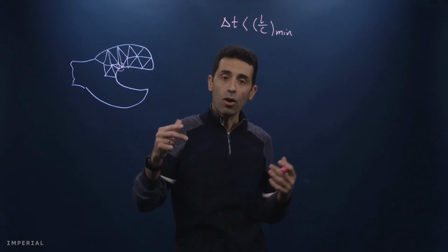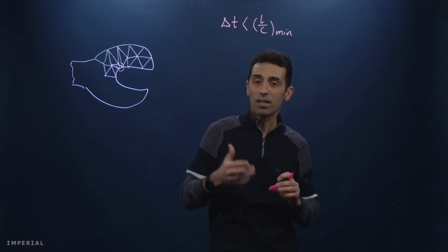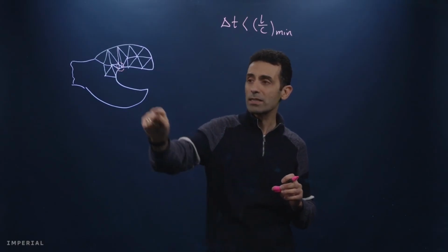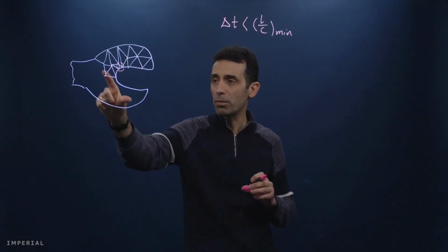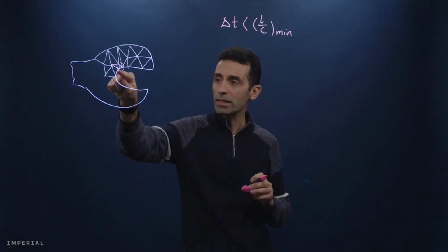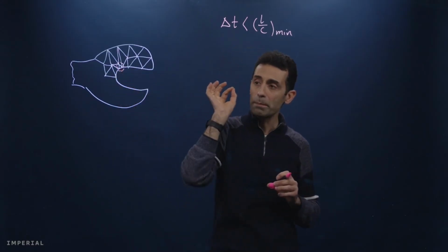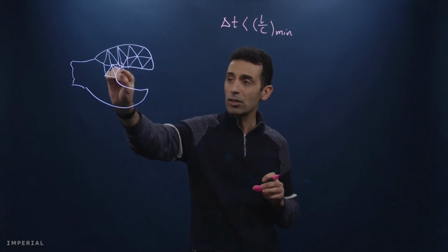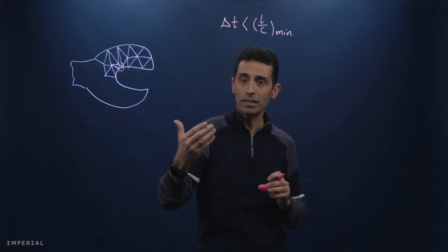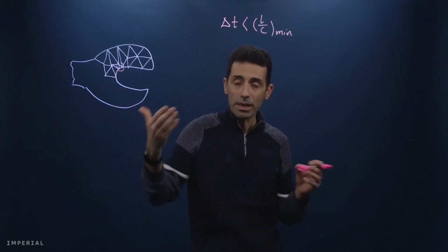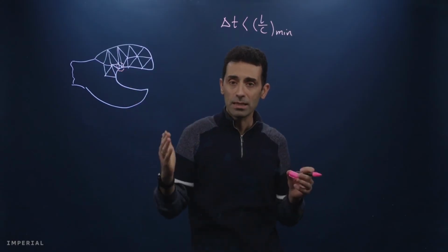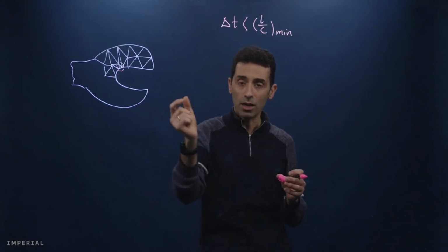These sort of elements are often created because of the constraints we have on the CAD. For instance, if in the CAD model of this body, we had lines here, then we are imposing having a node on the line when you are creating the mesh. Obviously, it depends on the application, but it may not be necessary at all to have such a tiny element.